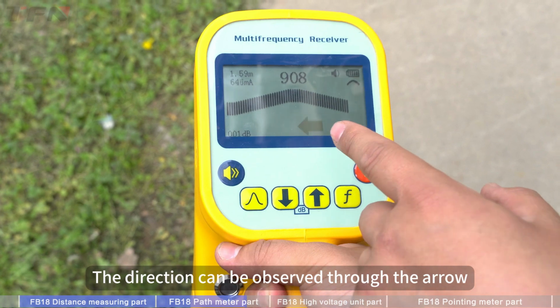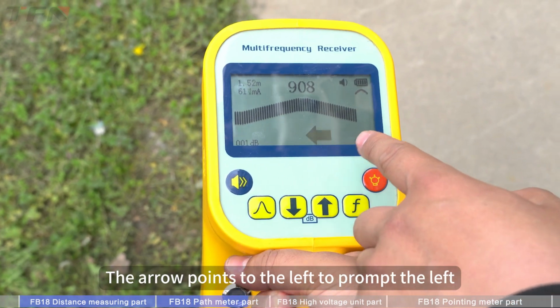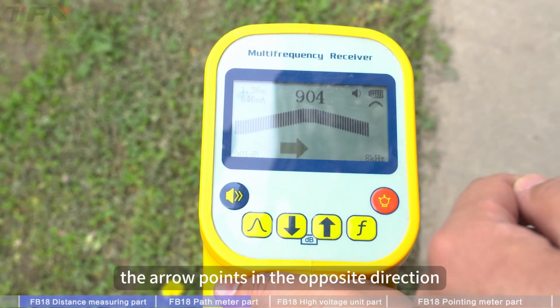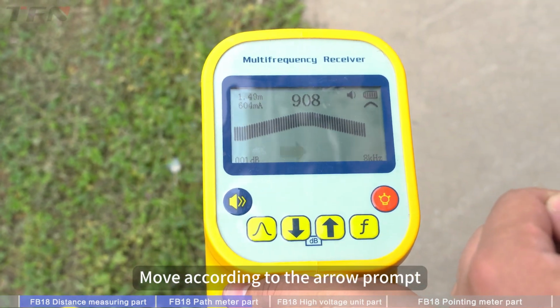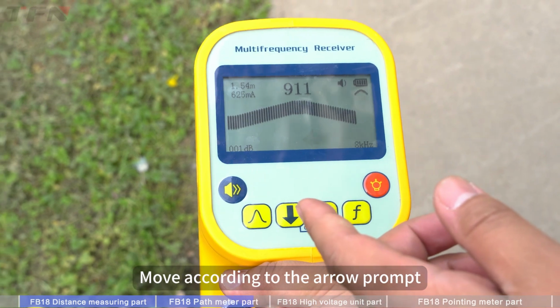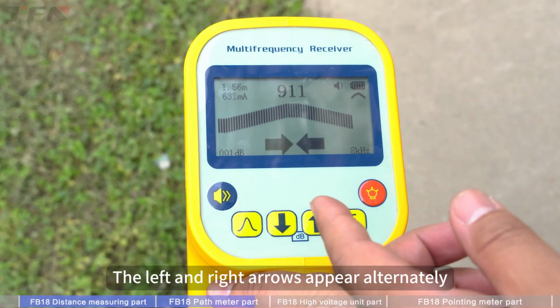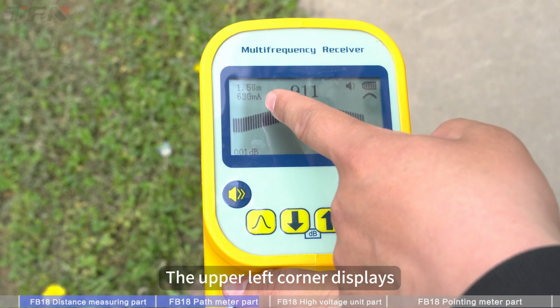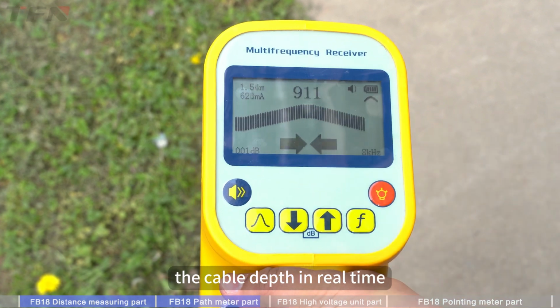The direction can be observed through the arrow. The arrow points to the left to prompt the left. When crossing the cable, the arrow points in the opposite direction. Move according to the arrow prompt. The left and the right arrows appear alternately, indicating that it is directly above the cable at this time. The upper left corner displays the cable depth in real time.